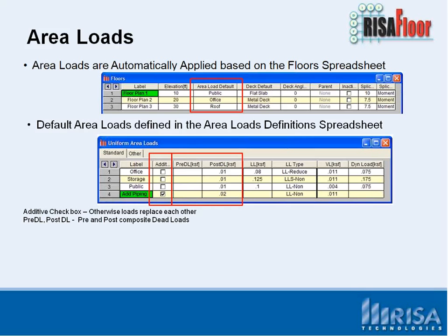The next option here is the pre-DL and the post-DL, and that's referring to our composite behavior. So that's pre-composite and post-composite dead loads. Okay, so we see here we only have some post-composites put in as the default.